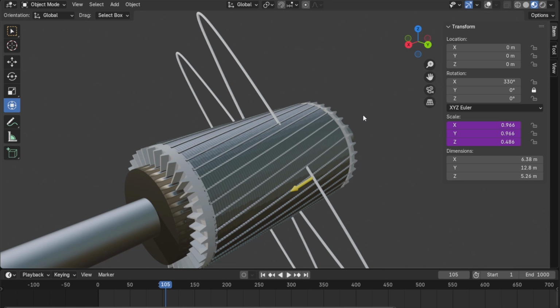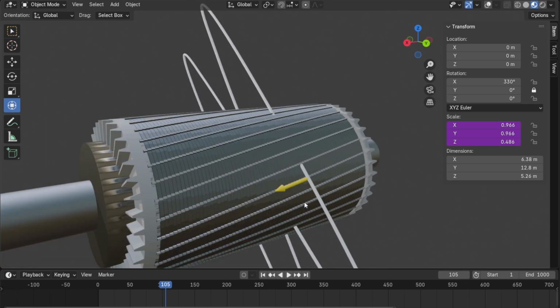And so that induced current, what happens when you get current? You get another magnetic field that opposes the one that created it. And that is the mechanism that allows this motor to work. So we're relying on the slip to magnetize the rotor for us. Okay. So what I want you to see is this yellow arrow right here. It represents the induced current in this specific rotor bar.